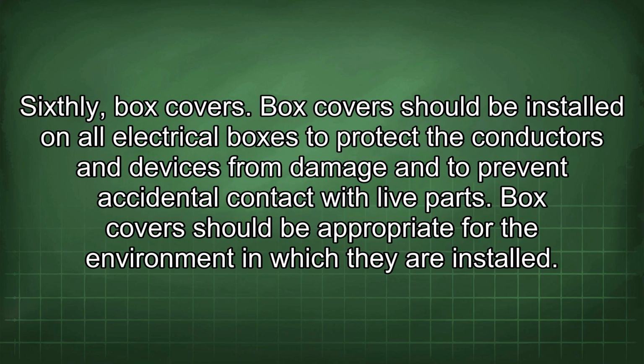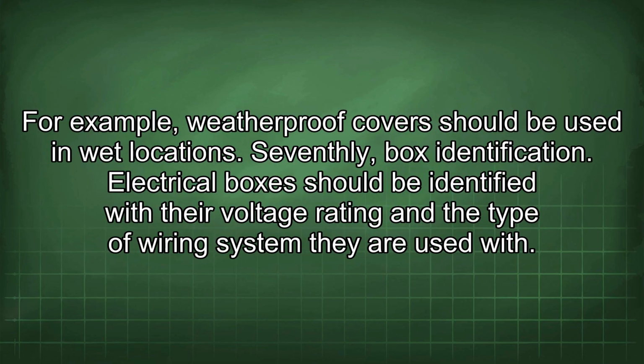Box covers should be installed on all electrical boxes to protect the conductors and devices from damage and to prevent accidental contact with live parts. Box covers should be appropriate for the environment in which they are installed. For example, weatherproof covers should be used in wet locations.